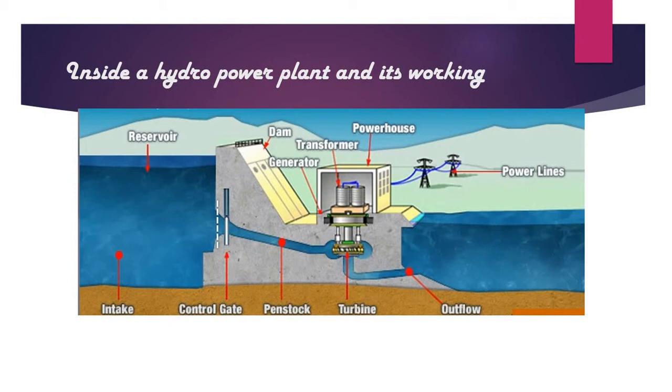Penstocks are usually equipped with head gates at the inlet, which can be closed during the repair of the penstock. A sufficient water head should be provided above the penstock entrance in the forebay or surge tank to avoid the formation of vortices, which may carry air into the penstock, resulting in lower turbine blade efficiency.